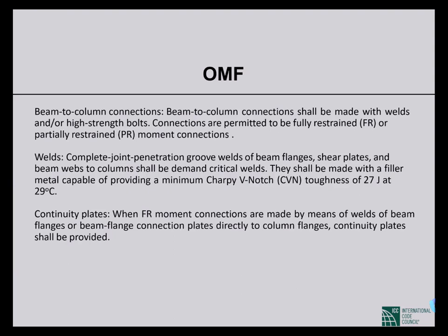Okay. Now, continuity plates: when FR moment connections are made by means of welds of beam flanges or beam flange connection plates directly to column flanges, continuity plates shall be provided. In BNBC 2020, which actually follows AISC 360-05, continuity plates were a requirement even for OMF when beam flanges are welded to the column flanges.